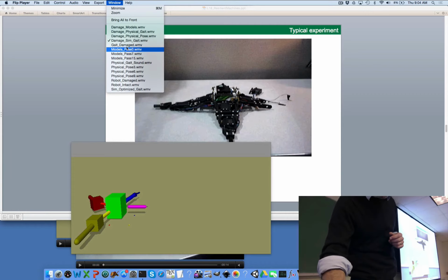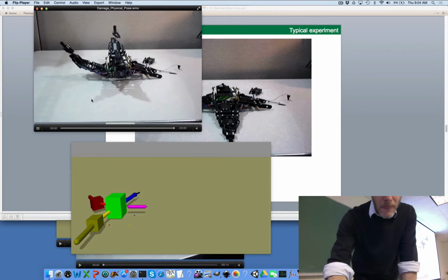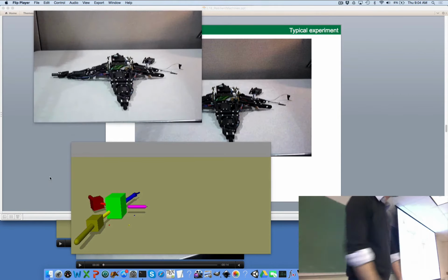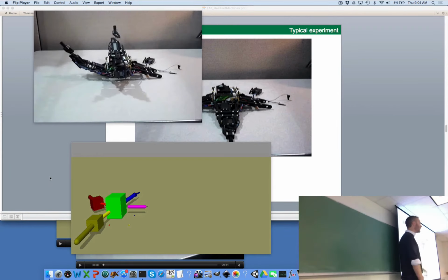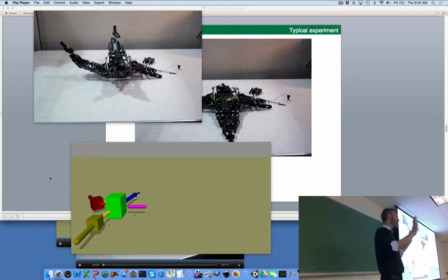Now we go in and damage the robot. And again, it doesn't have any pain receptors. It doesn't know that we mechanically separated the lower leg. There's no local sensor here that says this piece is missing. All this robot knows is that I performed this simple action before, and when I performed this action before, I tilted 60 degrees to the left. Now I'm performing the exact same action, and I'm getting a different sensory result, right? The moment it detects that, it stops moving and says, okay, I can't use that gait anymore.